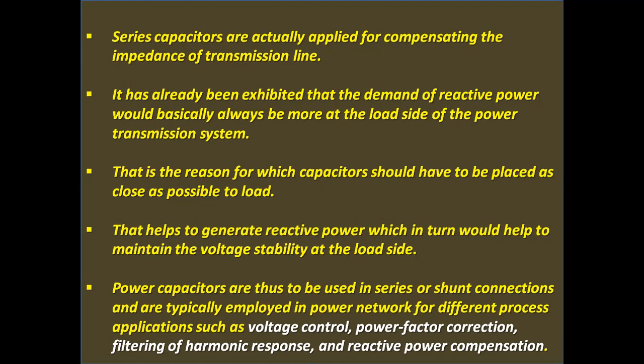Power capacitors are thus to be used in series or shunt connections and are typically employed in power network for different process applications such as voltage control, power factor correction, filtering of harmonic response, and reactive power compensation, the most important one.